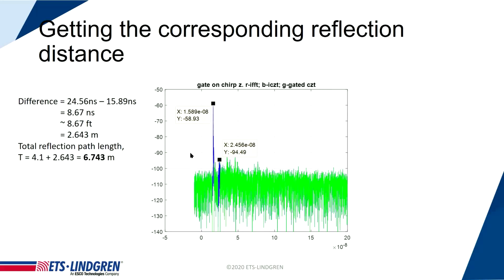So in this case, when I go back to this chart, I'm not sure what position. For example, this is at the top of the quiet zone, front position. You take this S21 measurement and then transform it into time domain. So this chart here is a time domain view. It's not labeled here on the x-axis, but the label should be time in seconds, 10 to the minus 9, so that's in 10 nanosecond steps. You can see around, in this case, 15.8 nanoseconds, there is the main antenna-to-antenna response.